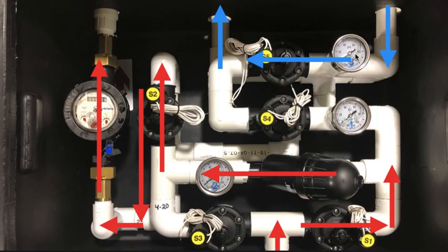And that's why, when this fifth valve is closed, we have pressure on this third gauge. This pressurizes when this flush line fills up with all that excess water. But now, when we're doing this part of the startup procedures, we're opening up that fifth valve and giving that excess water a place to go. So that excess water, as indicated by these blue arrows, now with the fifth valve open, allows that pressure to drop, and this water will go down the same way it did when we were flushing the disc filter, back to this vent line and back to the beginning of the system. And so that excess water will move fast enough to actually clean out those coils on a daily basis, and that's what we're looking at there.